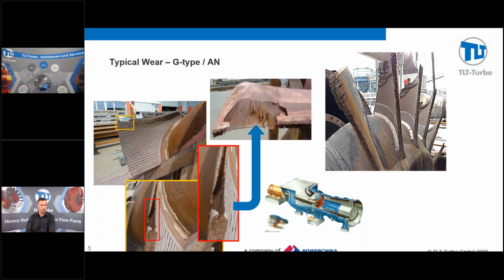So something else to watch for on wear is the reduction of material to actually cause the fan to go out of balance. Now, axial fans aren't as susceptible to this. They will see more uniform blade profiles. The wear patterns will be similar on all blades, unless you have large particles or a blade gets to the point where it gets thin enough that it actually breaks off or damages or goes through another blade. And then you'll start to see more imbalances, but usually they wear pretty evenly.